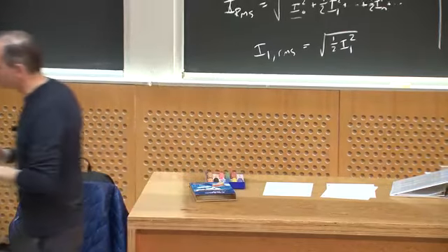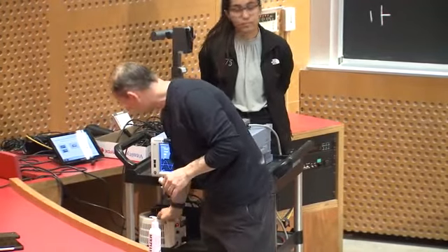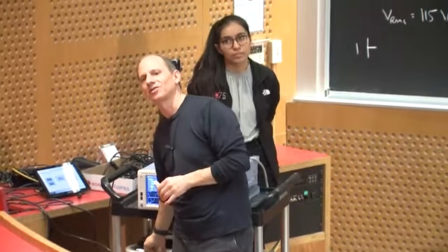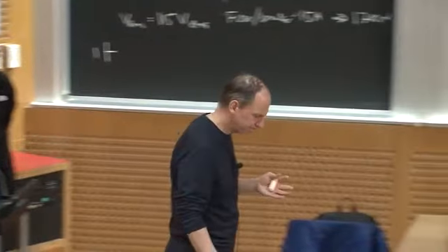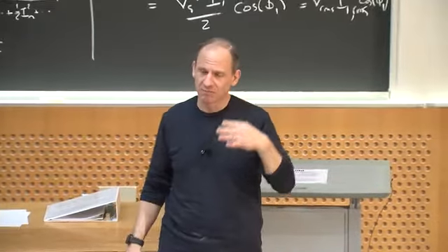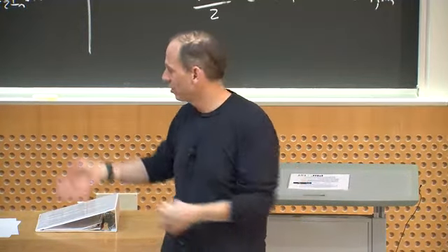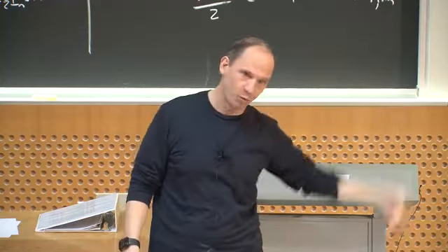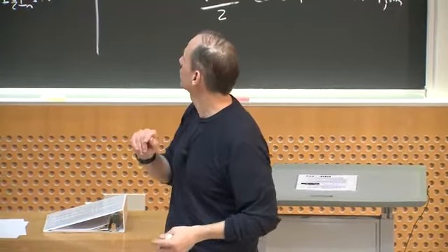So that's a very good question. In this particular case, we were running this through a variac, which lets us modulate the voltage a little bit. But the answer is, more broadly, the typical range of voltage is about -15% to +10% of the nominal. And in fact, if you're going to make a laptop power supply, you've got to make it go down way low because the line can be all over the place. The thing is, that's pretty sinusoidal, actually.